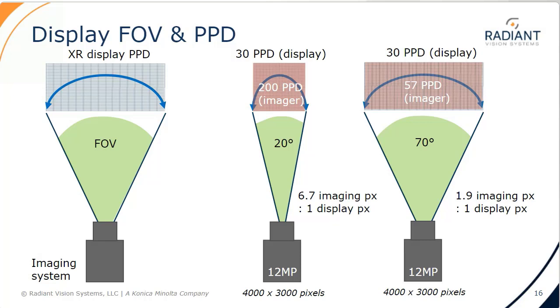A high-resolution imaging system is really needed in most cases to ensure that the measurement system is comparable with human eye resolution of 60 ppd, and that it exceeds the ppd of the XR display. The trouble is that many XR display test systems rely on relatively low-resolution cameras like these. These solutions also don't provide resolution optics. For instance, choosing a camera with more megapixels is needed when we have to measure a larger field of view.